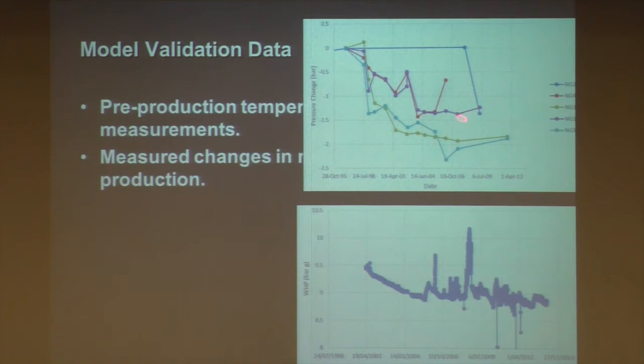The bottom plot just shows continuous monitoring that's been undertaken in that well, G13, that I mentioned. It's consistent with the downhole profiles that we see. From about 2001, we've had about half a bar of drawdown, which is from here to here. This well has a condition on it that the pressures are not allowed to fall more than 1 bar below the pressure in 2008. So they can't drop below 8 bars